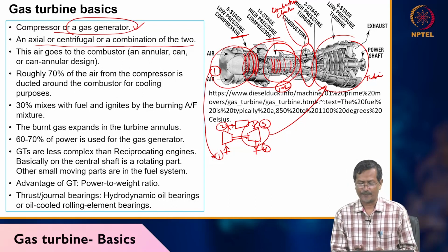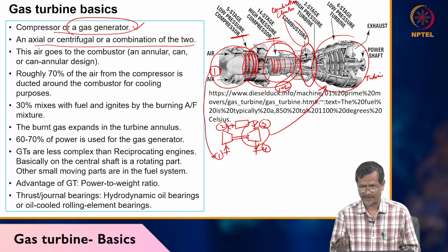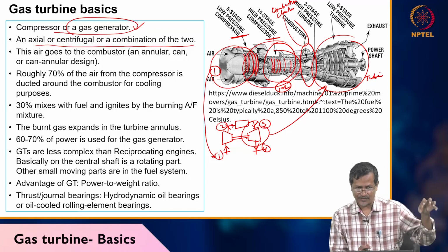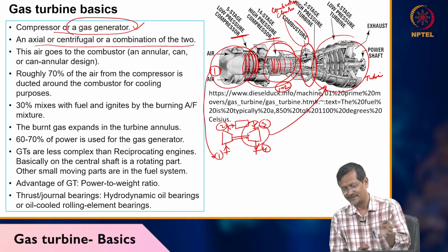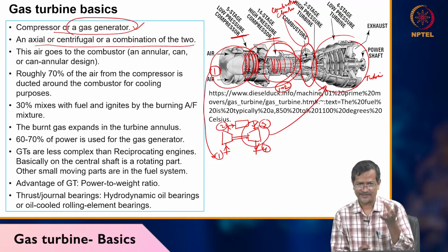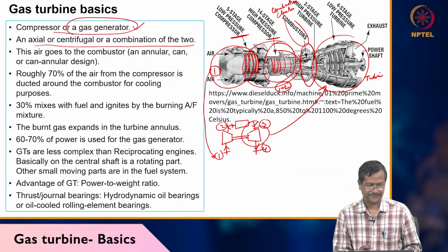In many compact engines people use centrifugal type, because centrifugal can develop very high pressure but has low volume handling capacity. So reduce the volume using the axial system, then put it in the centrifugal system and compress, increasing oxygen density. When you are compressing, you are giving more oxygen in a small volume into the combustion chamber.